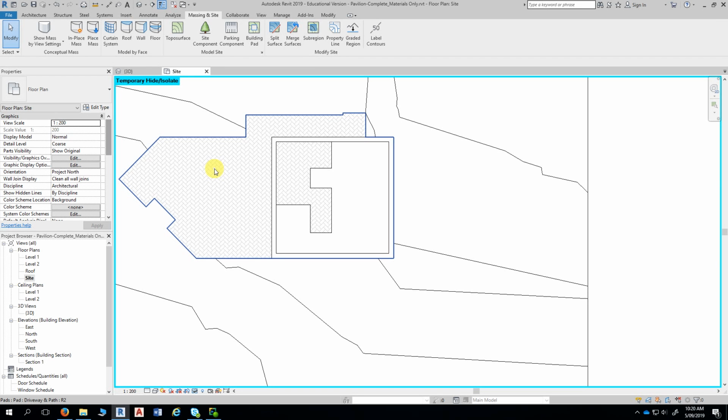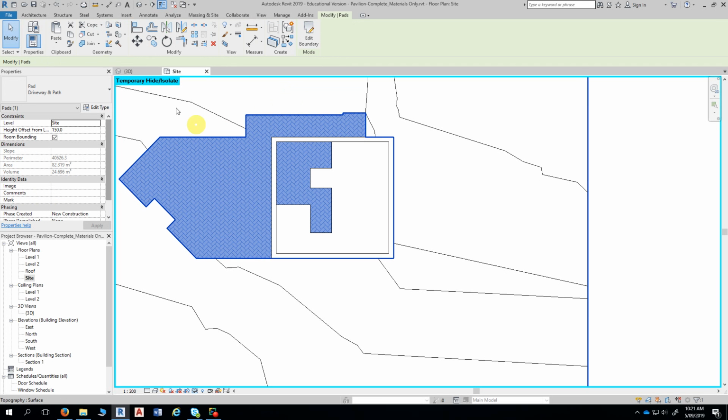Yeah. And as far as detailing the boundaries, you're going to go through that. Yeah, once the pad type is created, we then go through a process of sketching the outline of the pad to create it. Is that what you're getting at? Yeah, that's what we're going to do next. Okay. So step 1 is to create the pad types, and then step 2 is to physically draw them. Yeah, okay. Yeah, so I'll just swap this one back to pad 1.